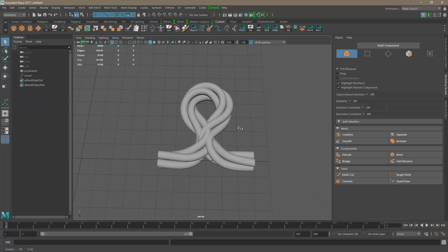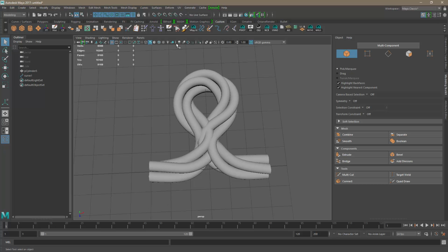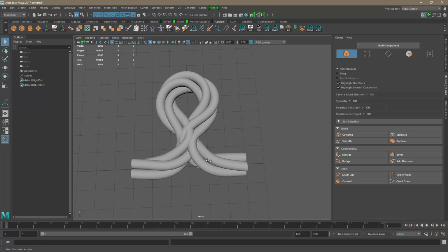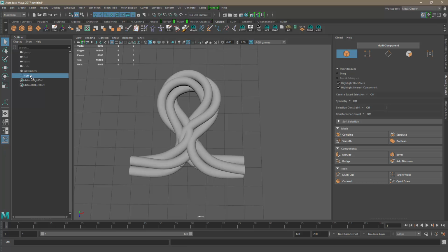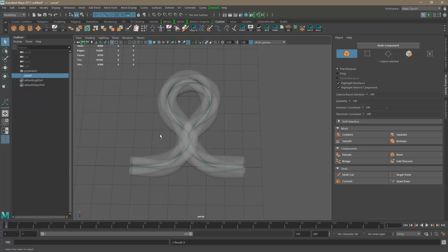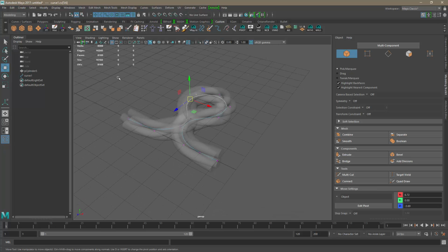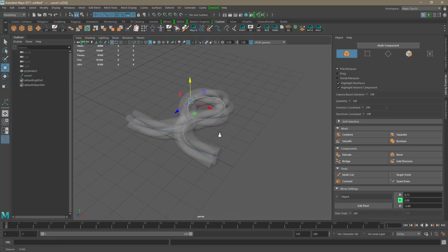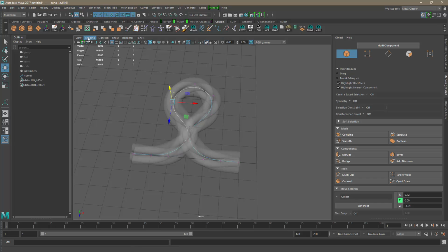Now, here's the interesting thing. This object is still active. What that means is, if I go here and click on X-ray with my curve selected, if I right click and go on control vertices and select these, for example, and move them around, you can see that it's deforming my shape. And there's also another cool thing that I can do.